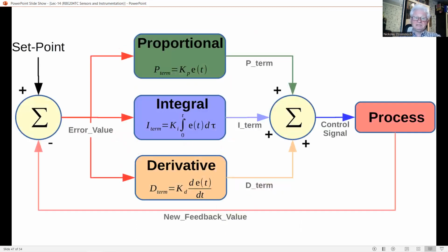Internally, a PLC performs basic computer functions such as logic, sequencing, timing, and counting. It can carry out simpler computations and control tasks such as PID control. Such control operations are called continuous state control, where process variables are continuously monitored and made to stay very close to desired value.